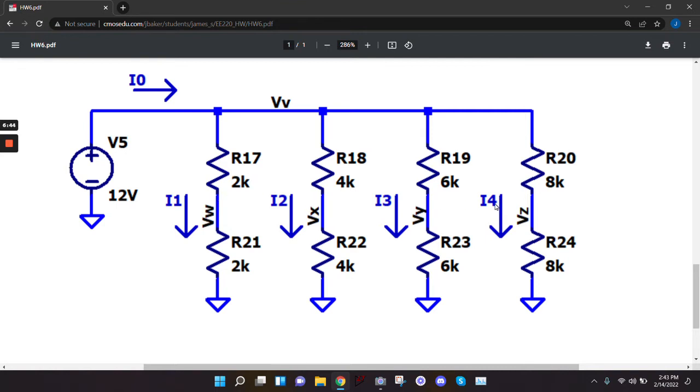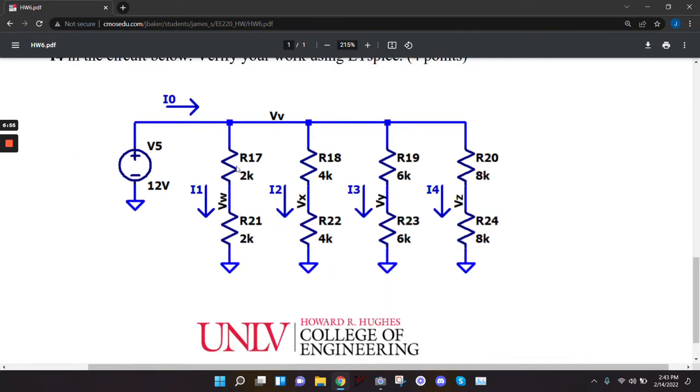This was 6. It's because it's just 4 voltage dividers. 4 voltage dividers in parallel. Yeah, they all start at 12, and then they get halved. So in every case here, yeah, this is a voltage divider, and what I want you guys to realize about this, that's good that you have that question. It means you did it right.